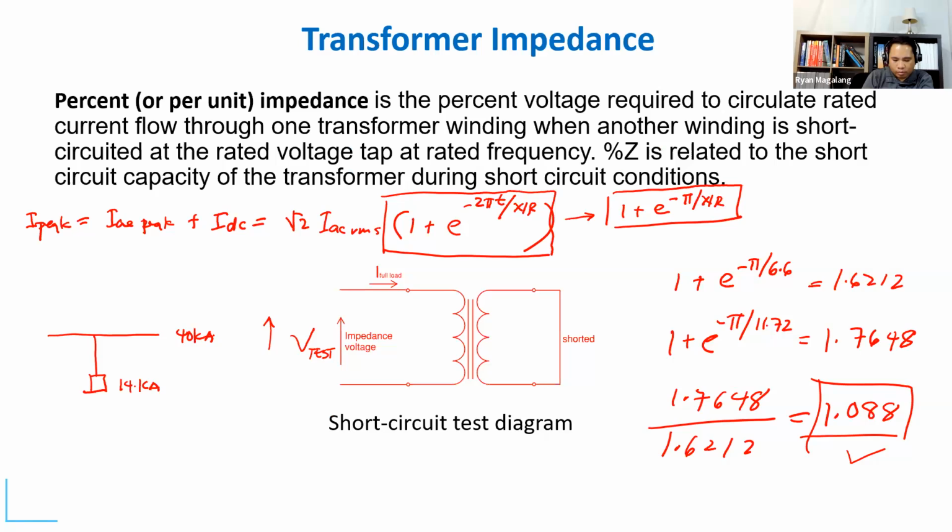One thing that you can do is obviously replace the breaker, and the other is to install a current limiting fuse here, a fuse that is capable of interrupting this 40 kA. Fuses normally have very high ratings, especially current limiting fuses. They are in the order of 100 kA, 200 kA or more, so it's almost never an issue.